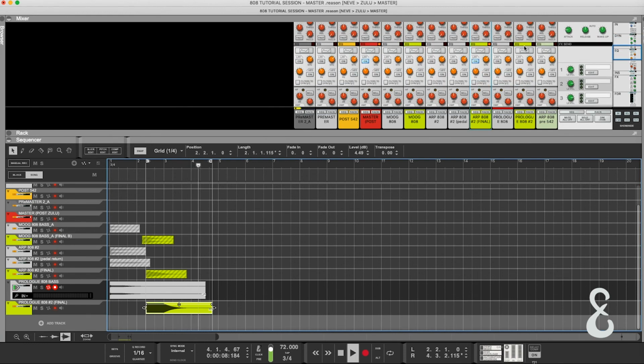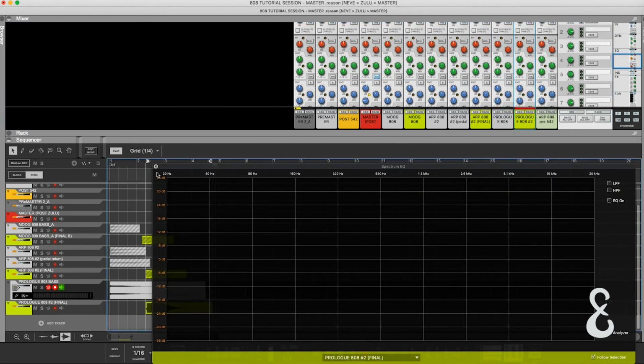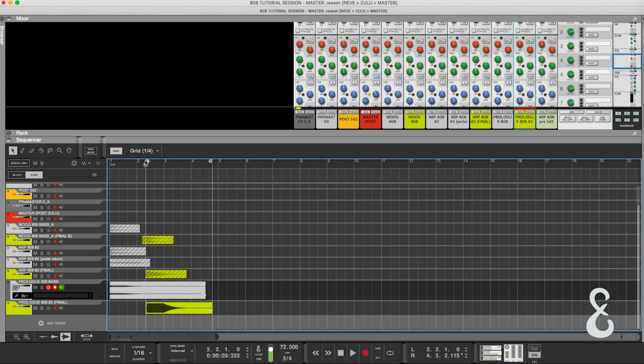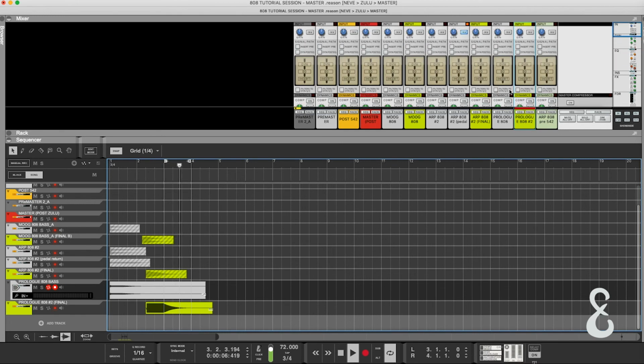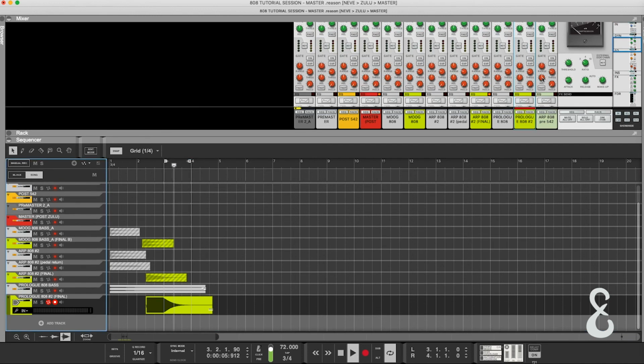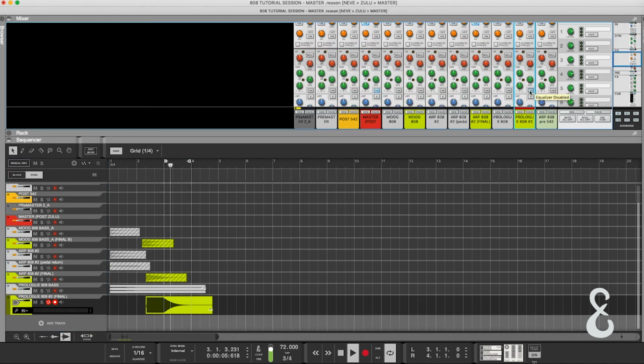Now, if you don't like the amount of noise on the high-end region, then you can always use a low-pass filter and filter it out. And let me show you an example of that. Just find out the frequencies that are screaming the most, the frequency band, and then use your filter to knock out that particular band. So here's an example, a technique of isolating the problem area, the area that you don't want.